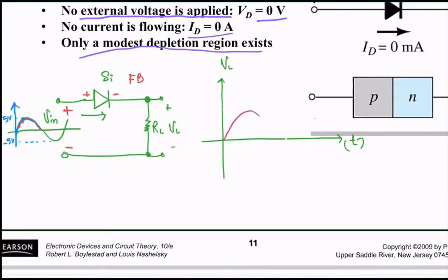It will be like this, correct? However, what about the magnitude? You get 5 volts here as the peak value, Vpeak is 5 volts, but you have silicon here. The silicon voltage drop is how much? 0.7 volts. So this peak value is going to be 5 minus 0.7, which is 4.3 volts, correct?